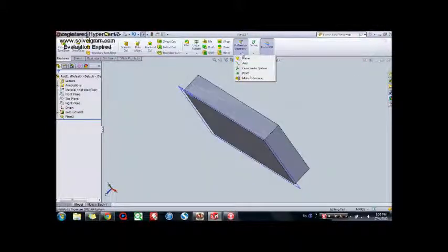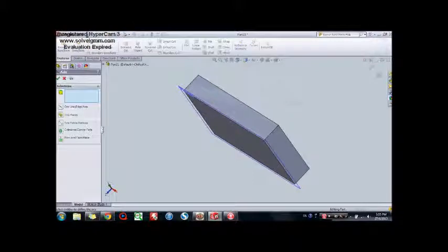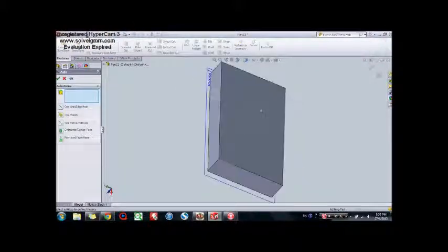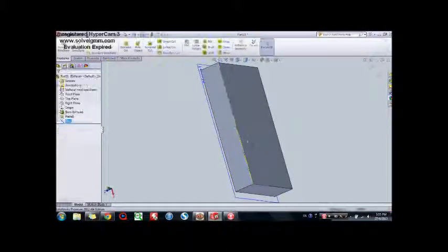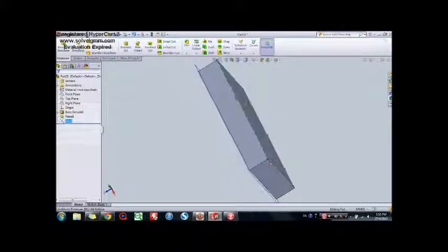So next one is axis. Axis is used to create a new axis on the object. There's a few options here, like one line/edge or axis, two planes, two points. I'm gonna start with one line. So I click on the one line option. I just click on any line or any edge of the object, like this one. When I click, just OK. There we go. You can see it's named axis 1.